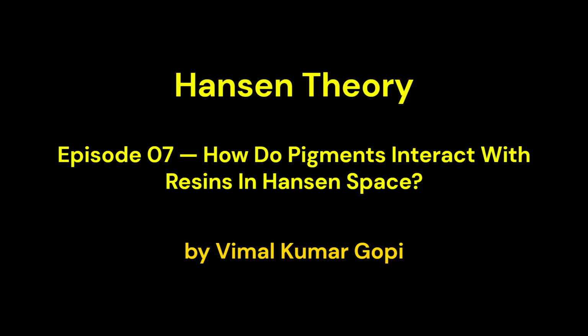Let's break this down. First, dispersion forces. Pigments with large nonpolar surfaces interact through dispersion. Nonpolar resins will wet these pigments effectively. Mismatch in dispersion leads to weak adhesion, pigment floating, or sedimentation. Second, polar interactions. Pigments often have surface functional groups: hydroxyls, carboxyls, silanols. These groups create polarity. Polar resins and additives are needed to achieve proper wetting. Ignoring polarity leads to partial dispersion, poor gloss, and film defects.